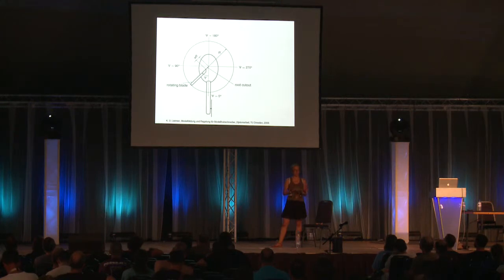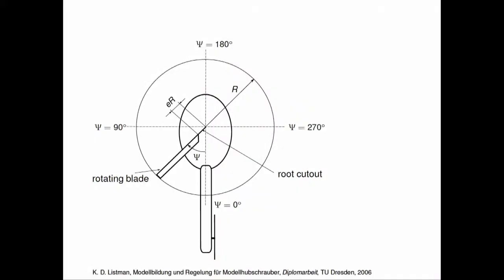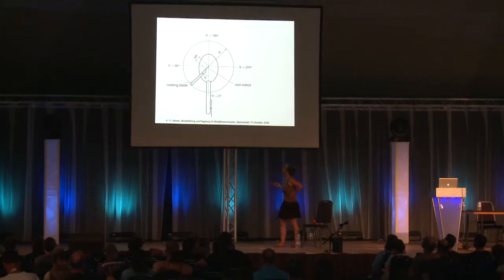They have propellers, and helicopters have rotors. So they have a cutout in the first part. You have to integrate beginning here to the tip of the blade, and you don't find that with propellers. Furthermore, there are some nice effects happening at the tip of the blade. You have some vortex effects and tip loss effects, reducing your thrust.